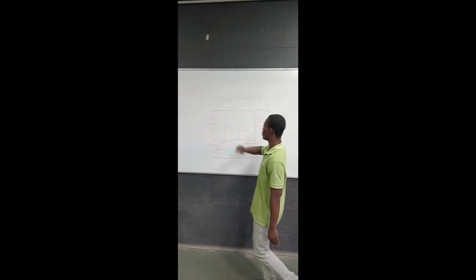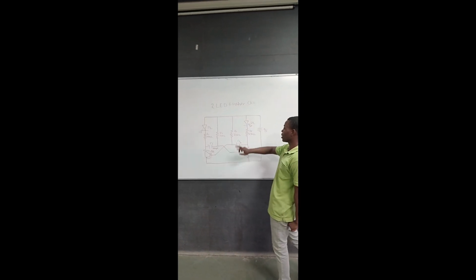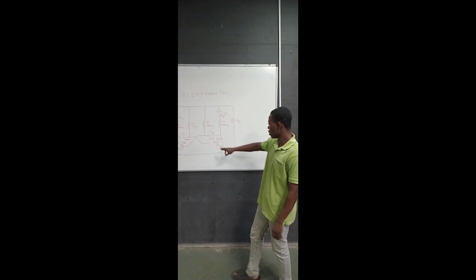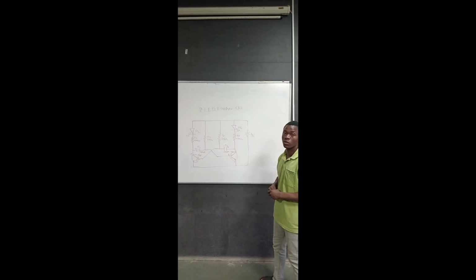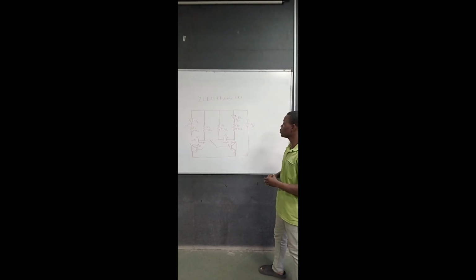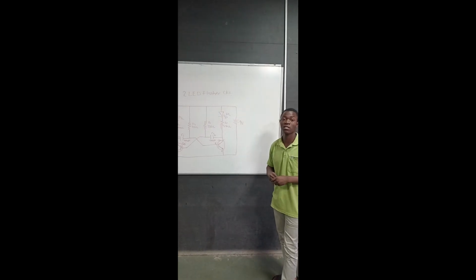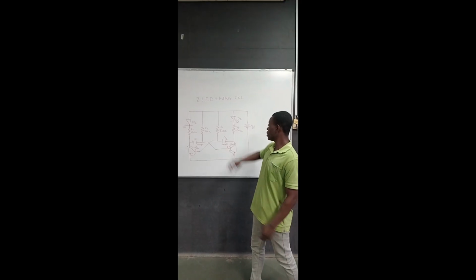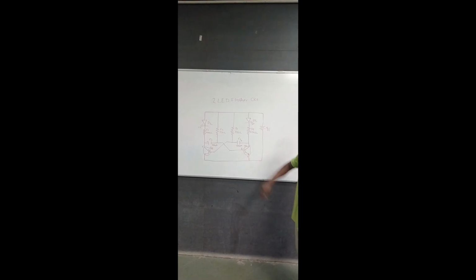Then we come here to our resistors R2 and R3. Both of them, as you see, are 22 kilo ohm resistors. These resistors are connected to Q1 and Q2. Their operation is to control the switching behavior of these BJTs by controlling their base currents. Resistors R2 and R3.